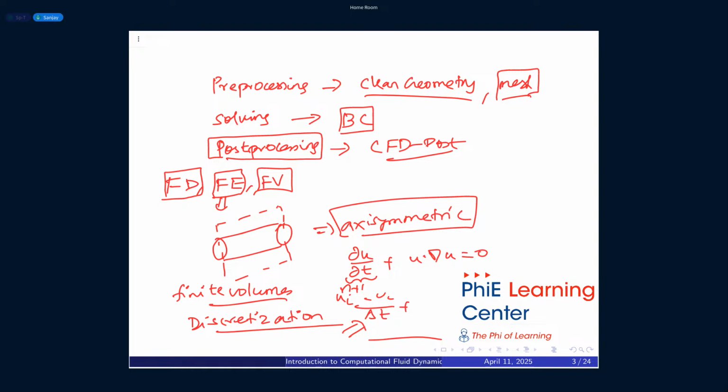We also have initial conditions in the solving part, because if the problem is unsteady, we have initial conditions. When I typically mention the boundary conditions, it also typically incorporates the initial condition as well. Okay, so broadly speaking, you can divide the problem into a steady and a transient base. So in steady problems, you don't have to worry about the time stepping and all sort of things. Whereas in a transient problem, you have to worry about the time step size and all sort of things. Okay, so fret not, we will be looking at that in detail.